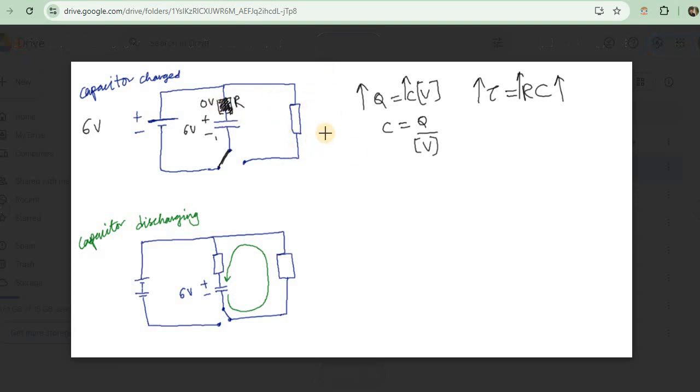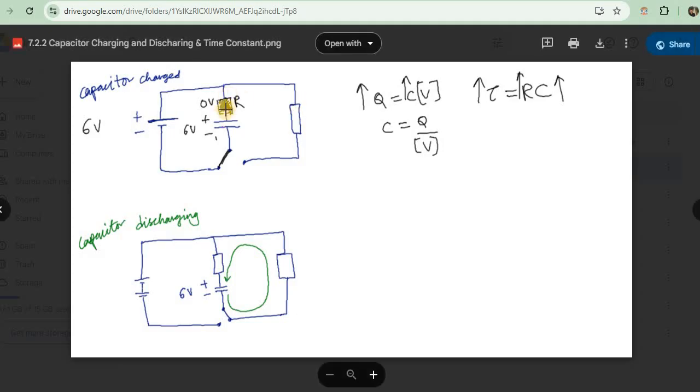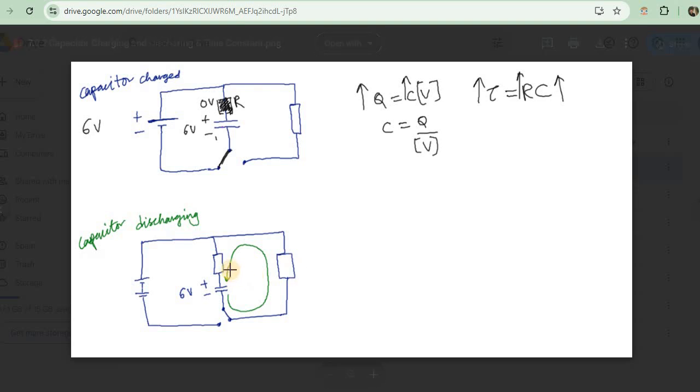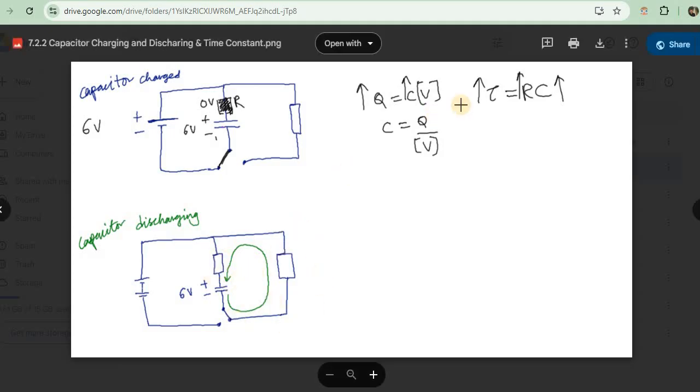Now in this case, we don't need to draw two resistors here. We can simply have only this resistor. We don't need to have another one here, so that when it's charging and also when it is discharging, the current flows through only that single resistor always. Okay, so here you can see the switch is connected so that the capacitor, resistor and the cell are connected in series, and this will charge the capacitor. But here you see the cell is not connected with the capacitor, so here the charge stored on the capacitor will discharge through this circuit. So we will see the details afterwards.